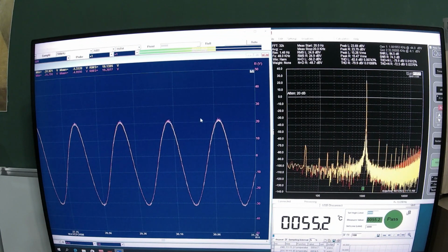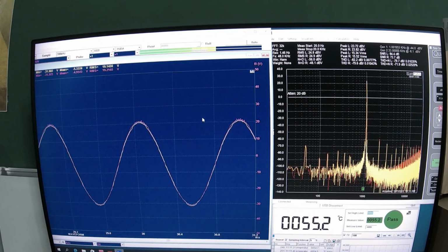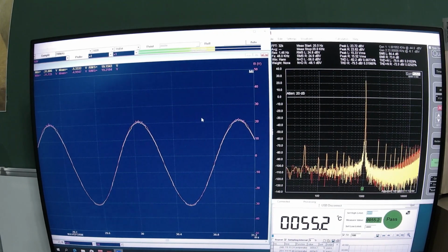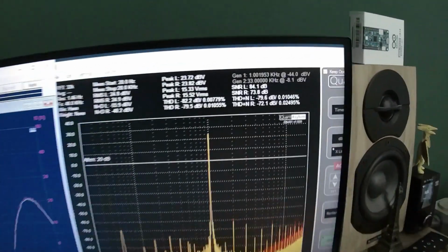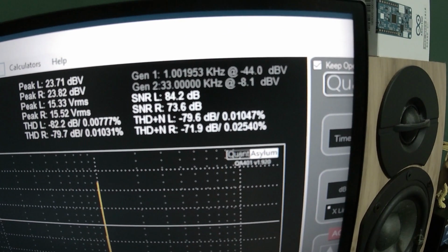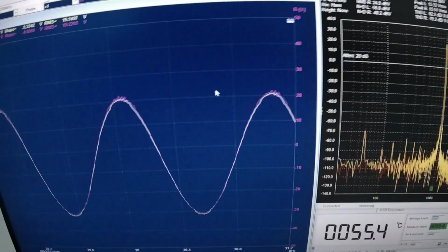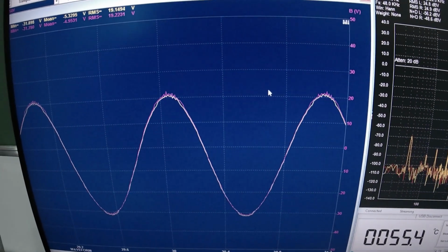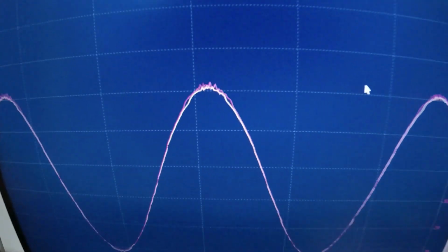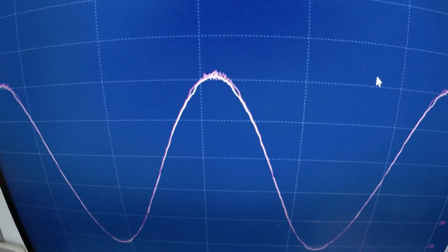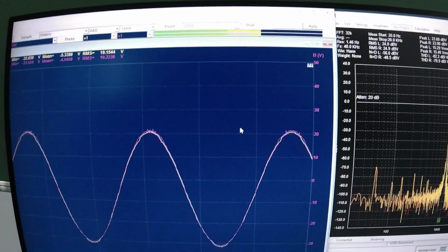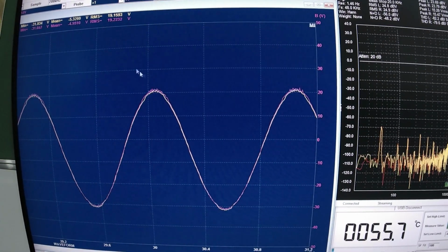All right, to be fair, that's 19 volt RMS of the output, and we still see pretty good distortion in here, about 0.1 or 0.2 on the right channel. Why is it so? Why is the right channel higher in distortion? That's the evidence. We can see that one. Let's see that closer. Yeah, let me position that one.